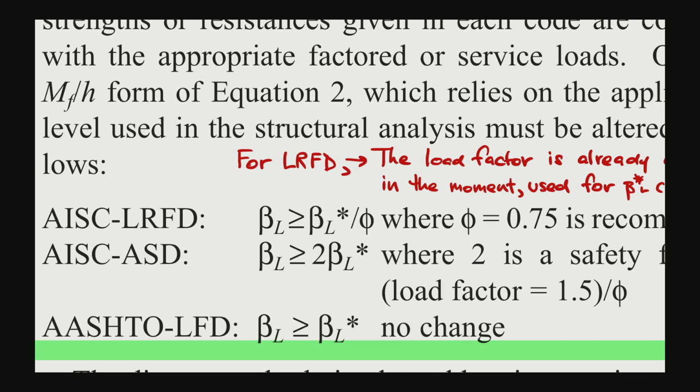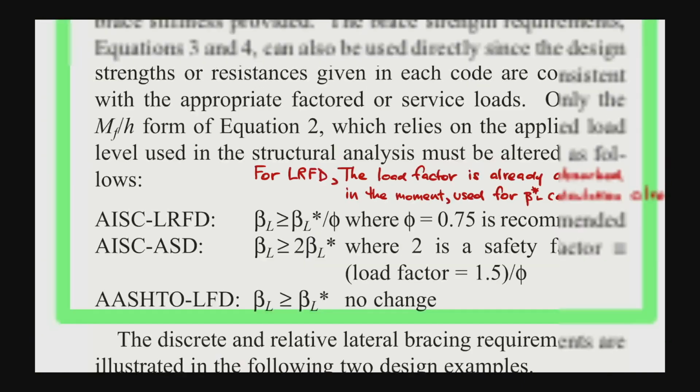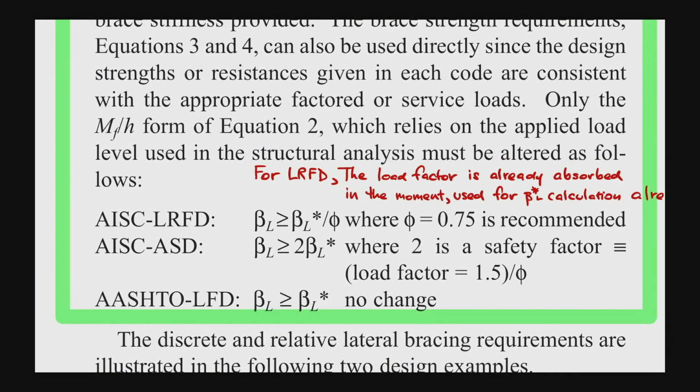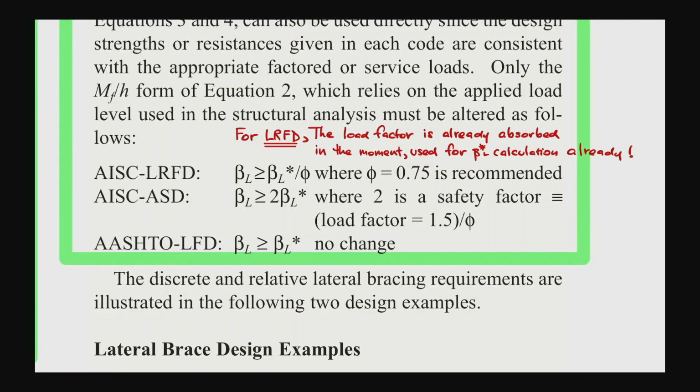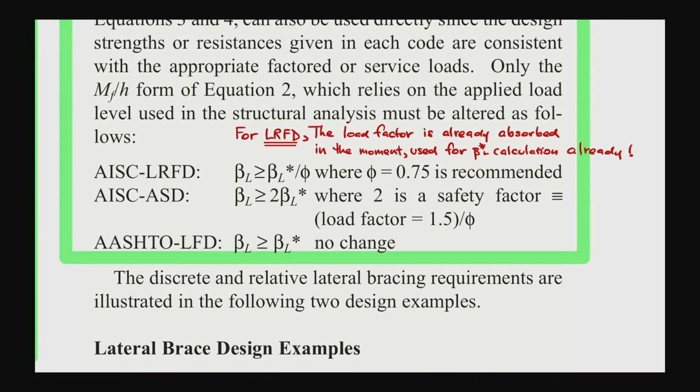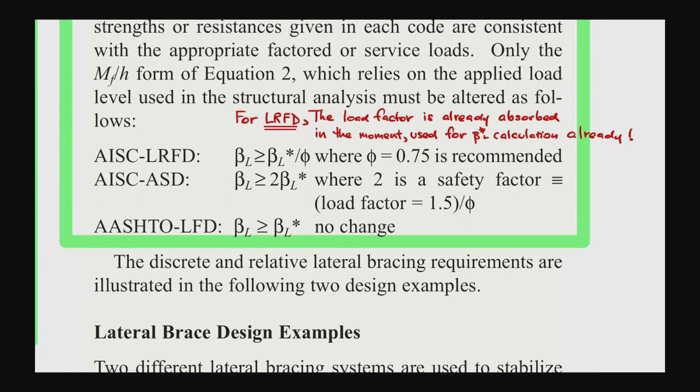Okay, to make it clear, to avoid any confusion, for LRFD, the load factor is already absorbed in the moment which is used for beta L calculation already. So you just need to divide by 0.75.